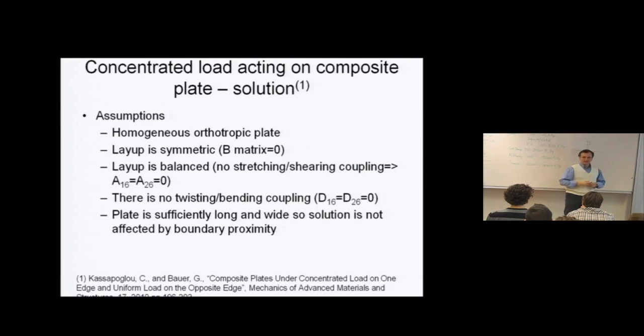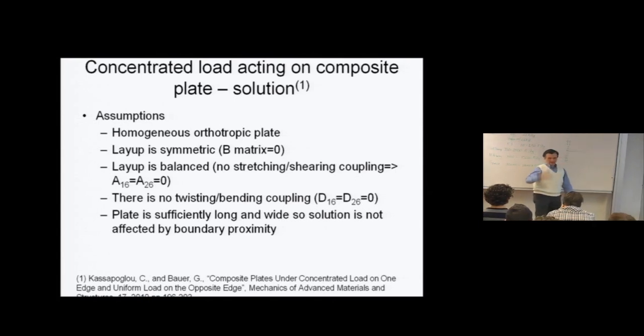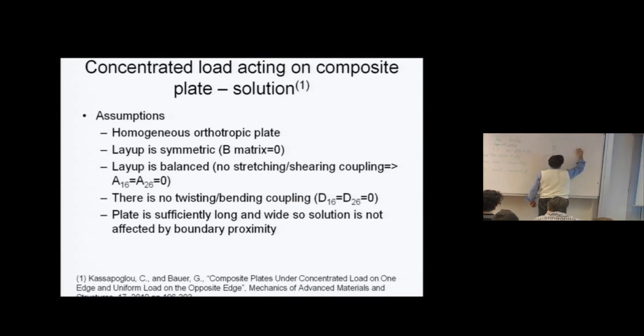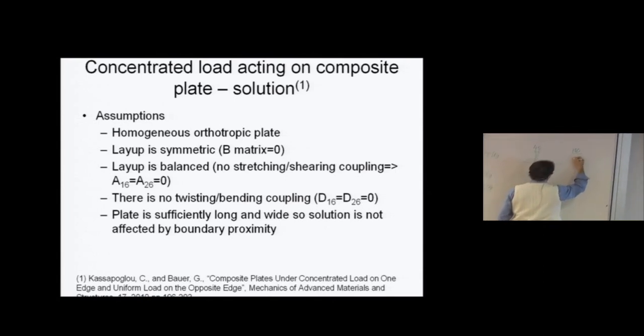But instead of having an infinite number of fibers distributed every degree, you can do it at certain intervals of degrees. So the quick way to do this is you take 180 and divide by n divided by 2. If you have n layers, you divide by 2, and then you divide that into 180. I haven't told you what n is. The example in my mind is 8, but don't worry about it. That tells you that you need fibers every so many degrees. So if n equals 8, 8 divided by 2 is 4, 180 divided by 4 is 45.